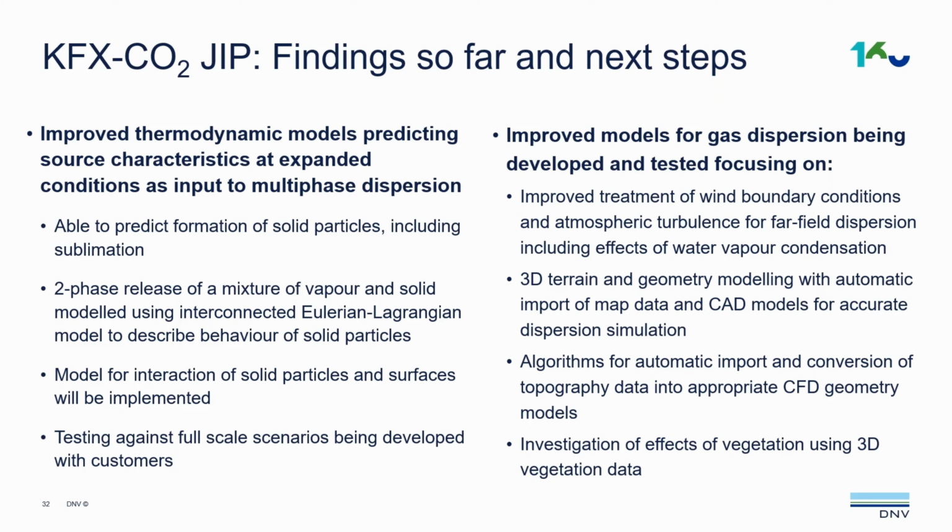So the activities focus on one side on improving the source term modeling so that KFX can model multi-phase release, taking into account dry ice particles in the gas flow, but also deposited solid particles on the ground. The other part is to improve the models for gas dispersion, specifically the treatment of wind boundary condition and atmospheric turbulence for far field dispersion, including the effect of water vapor condensation. And of course, as mentioned, we need to be able to account for geometry, so buildings and so on, terrain like hills and valleys, but also vegetation.